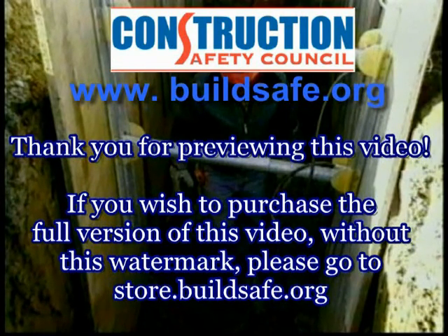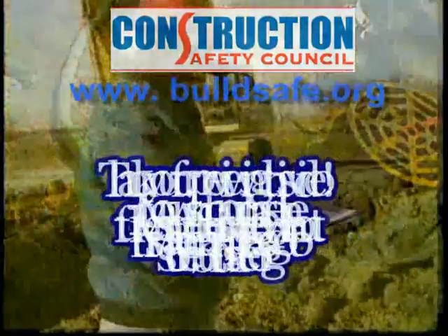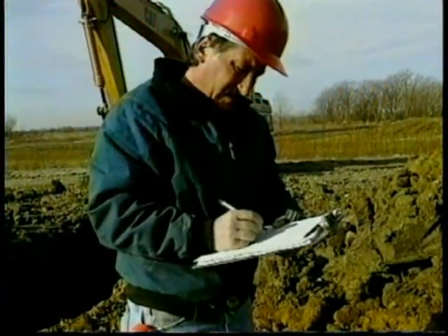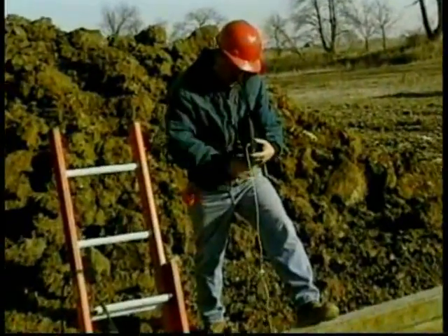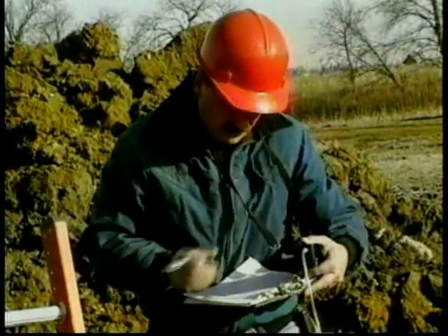Never let water stand or accumulate in an excavation. Always have water removal equipment ready and in working condition. In general, inspections should be made and documented as needed throughout the day. If any hazards are found, they must be eliminated before work can proceed safely again.